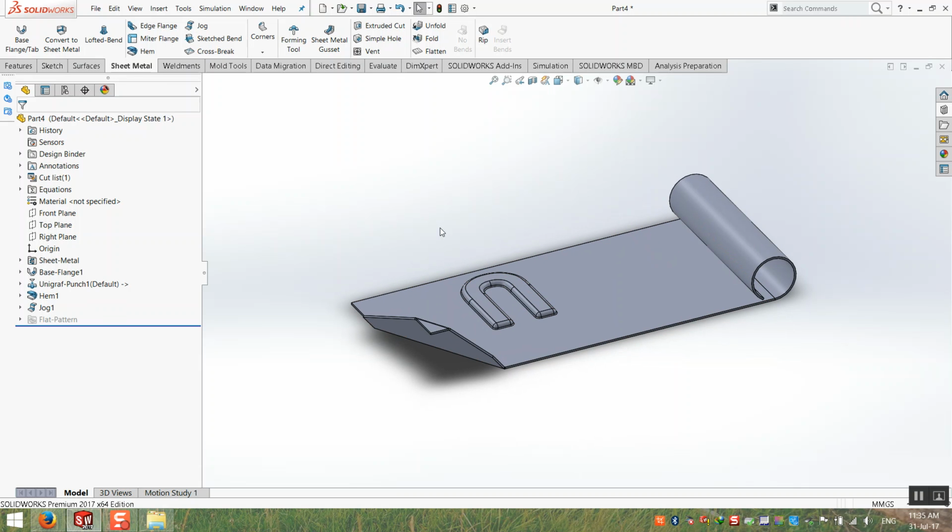If you notice, all these features draw the sheet metal in bending mode, meaning that you will start with your own flat and bend edges. But if you have a special case where you already have the flat sheet, and you need to bend it like a press brake, you can use this one.